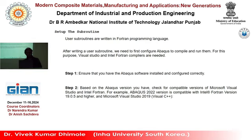Okay, when you check the compatibility, download accordingly only. If you see 2022 and you download Microsoft Visual Studio 2018, that will not work, and you say I have it but it's not working. Check the compatibility, install it properly with the administrator permission, define the edit environmental variable, then properly check the directory, check the subroutine file and run it, it will run.